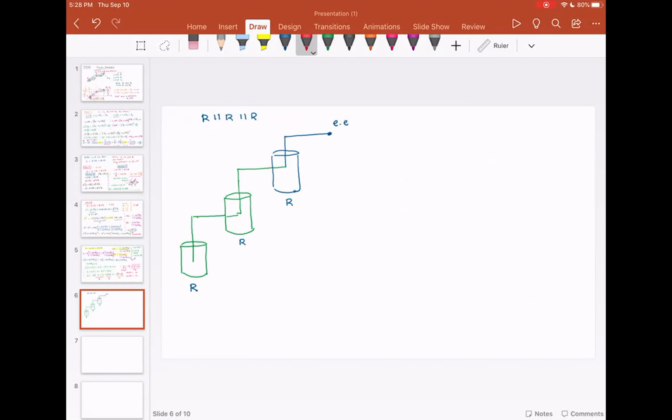So let's solve the forward kinematics problem by assigning frames. This is going to be my Z0, this is Z1, this is Z2, and this is Z3. Then let's add the x's. This is x0, and remember we have to follow the rules, so x1 has to be perpendicular to Z1 and Z0.